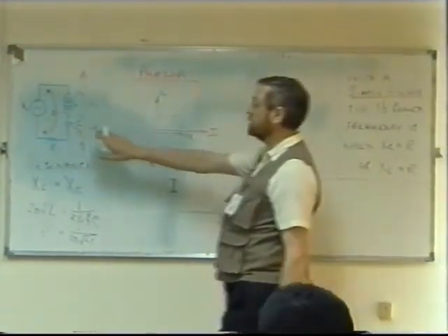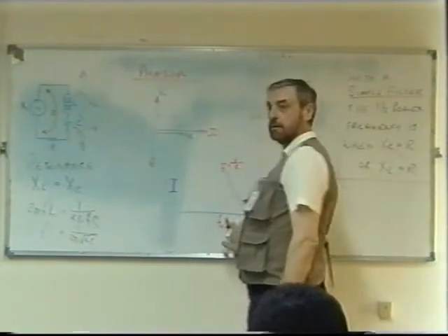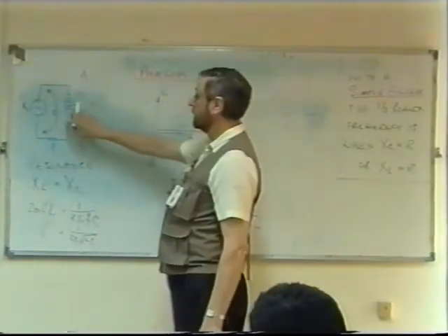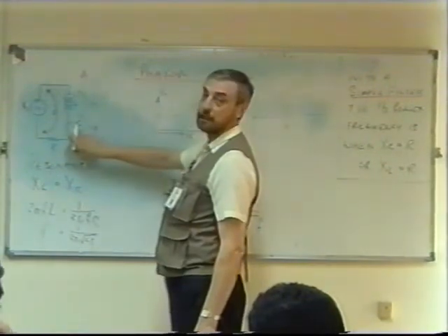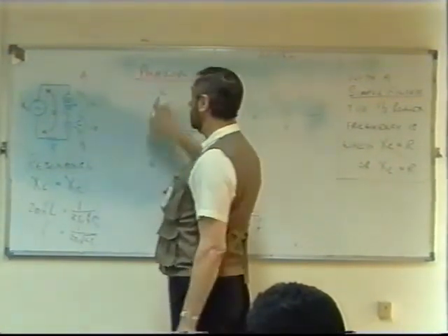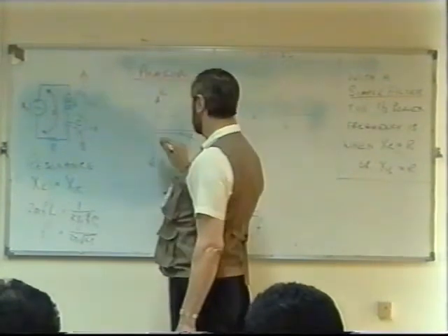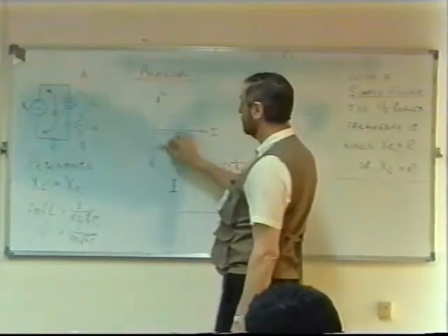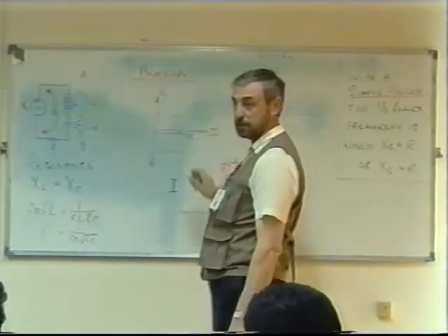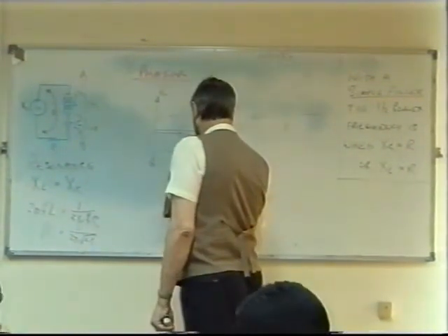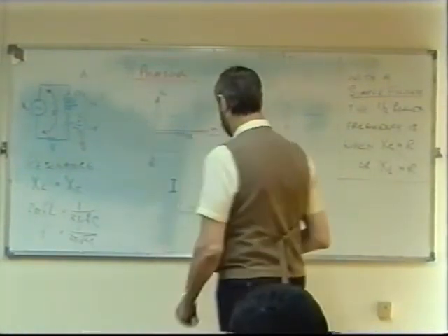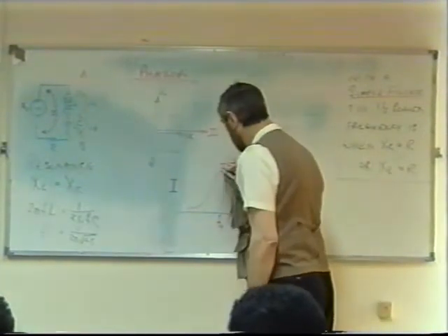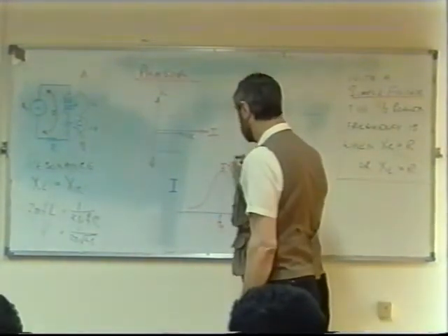Now, if we decrease the frequency below the resonant frequency, the opposite will happen. XL is decreasing, XC is increasing. Again, we get a difference between the two, only in the opposite phase. Our total impedance will be the sum of our complex impedance, and therefore, again, reduce the current. So we get a waveform of something a little bit like this, where this frequency is about resonance.